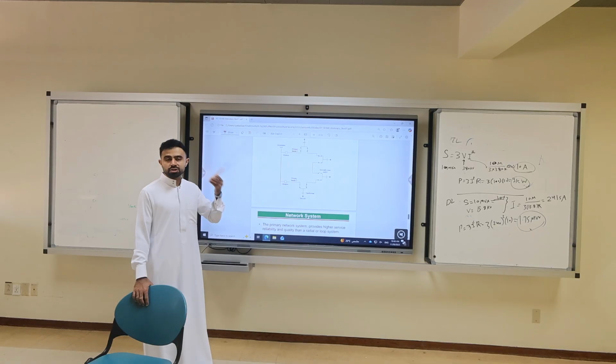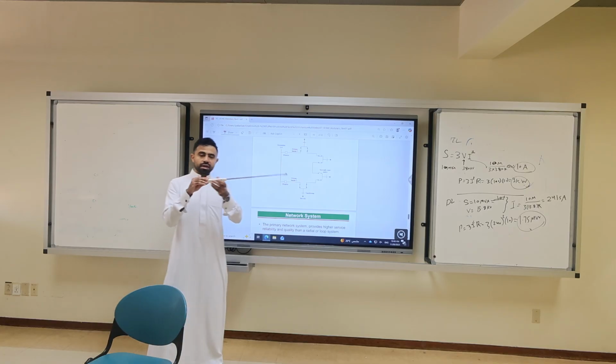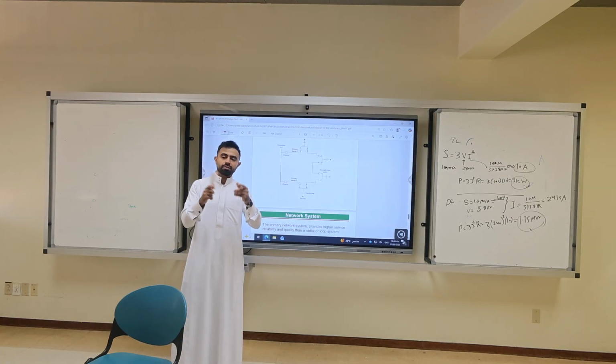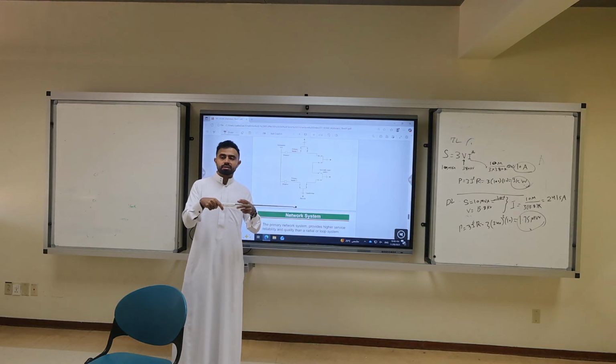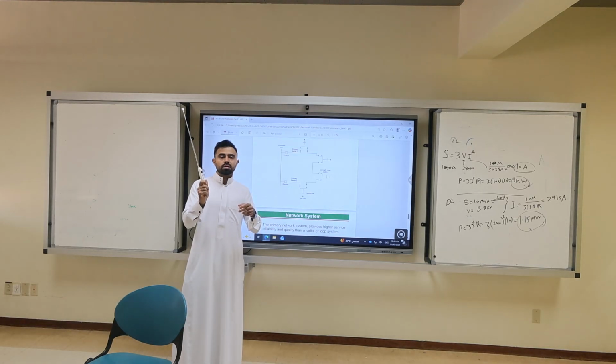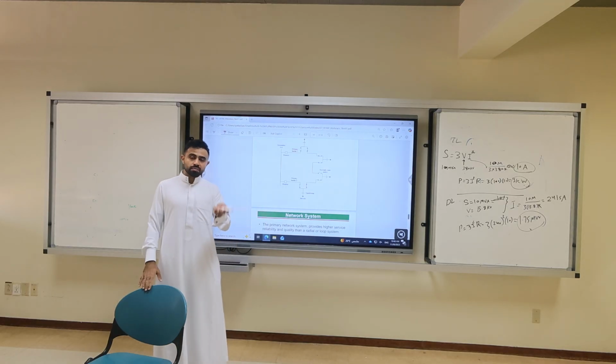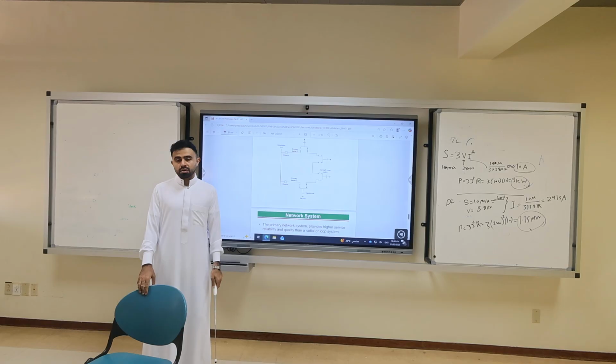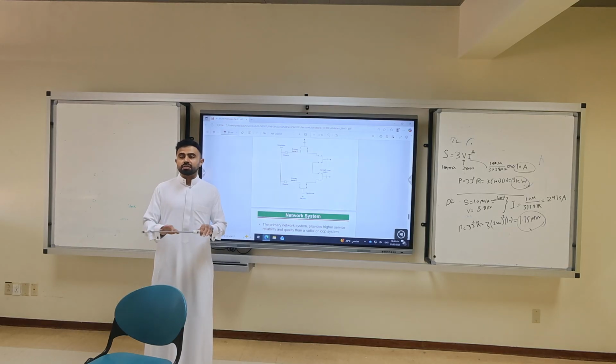The recloser is an automated switch. The way it works, it will sense the voltage and the current. If it receives a signal from the relay, it will open. Count 4 cycles. Reclose. Get the data. Good or bad, still bad, open. On its own. Then it closes again. 3 times usually, and then it will be permanently open. So what will happen is you have to close it manually. If it's underground, who will close it? The power system is not automated. Everything is automated? No.